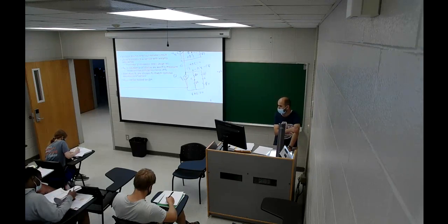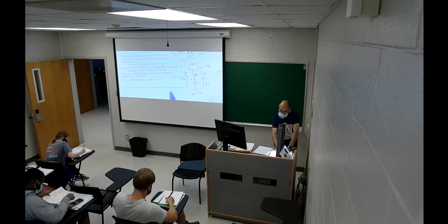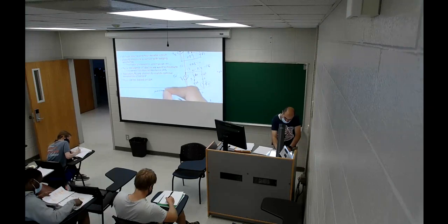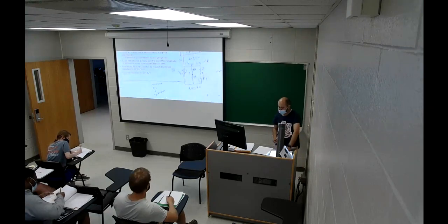We will use this to find the unknown resistor, or to measure the resistance. Why are we using this? Because sometimes we have a thermistor or a photoresistor, which are resistors that change, or sensors that have resistors changing with temperature or with light. How can we measure this? How can we convert this to electrical energy by using the Wheatstone bridge? So the target here is to measure the unknown resistor, Rx. So that's what we will use here.